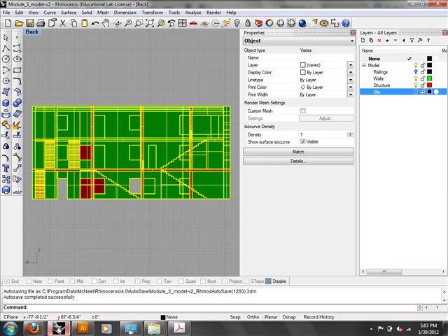I'm sorry. A lot of people in my class had this problem with selecting visible in the perspective plane. Yeah. What it would do is skew lines, not add lines, take away a wall. And for me, I wasn't even allowed to choose select visible. I had to select all. Yeah, select visible has some problems. If it doesn't work, you have to do select all, and you just have to deal with it. Again, we're kind of abusing it for what it's used for.